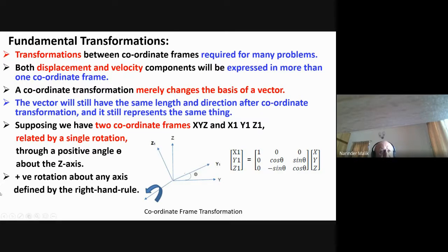For example, satellite position and velocity components are expressed many times in more than one coordinate system. I'll give you an example. The magnetic field model of the satellite is available in a particular coordinate system called NED, and you are carrying out everything in the computation in the ECI frame. So you have to transfer the spacecraft orientation information to the NED frame, find out the attitude in that frame, and then bring it back.